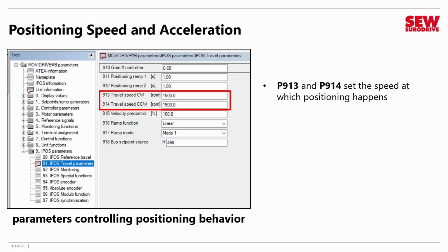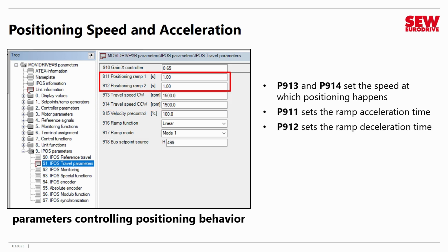As you recall, since I had a servo motor, I set mine to about 4,000 RPM. That was about 10% less than the motor's maximum speed. Of course, you can certainly pick slower speeds if you want. You don't have to pick maximum. That was more an upper limit, but right now it doesn't really matter. Simply be aware these are the two parameters that you have to adjust to pick the positioning speed that you wish to use.